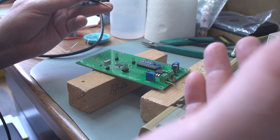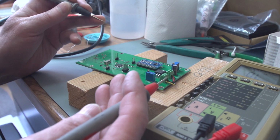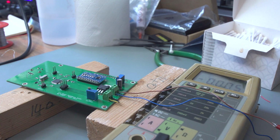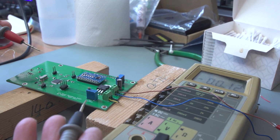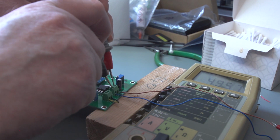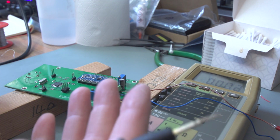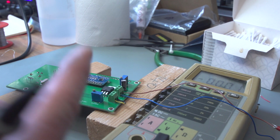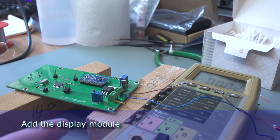We know we don't have any dead shorts or anything nasty going on, so it should be safe to apply power. So let's do that. Alright, so the board is now powered up. I'm just going to check, make sure we've got power to the board. Yeah, we've got 5 volts there. No magic smoke, no disasters. So I think we're ready to go to the next step.